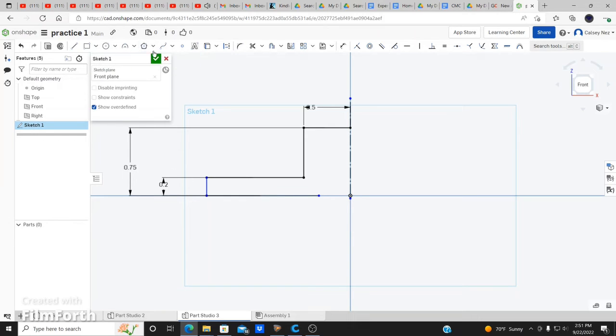Most of the time, it'll have no indication of those hyphens because they don't actually have commands or shortcuts for those ones. It's kind of difficult because they have the same letters for specific other tasks too. Squiggly, spline, point, fonts, project curves, and also dimensions, which is D. So I would just select those letterings right away. I'm going to select L. That'll be my line. Bring it up here, press escape on your keyboard, and there we go.